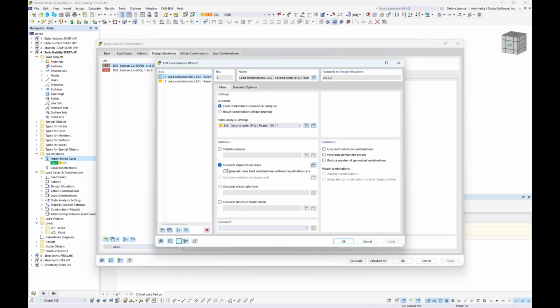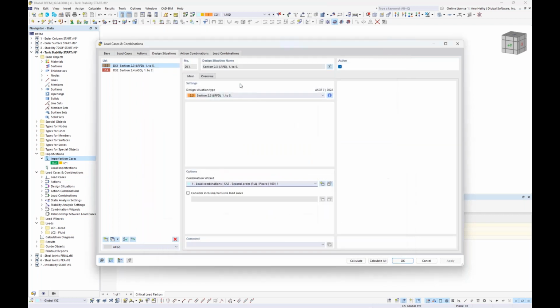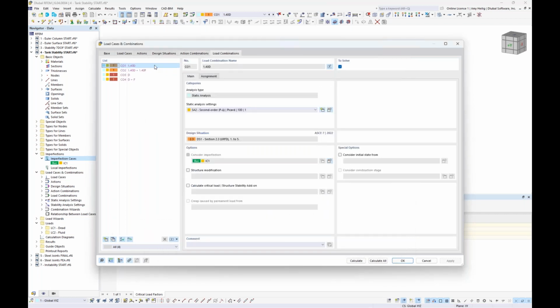And this is typically by default always checked on. So now when we go to our load combinations individually listed out, we see this imperfection automatically considered. So again, when we take a look at load combination number 2 here, we are going to first deform the mesh based on that buckling mode and the scaled magnitude that I had put in.